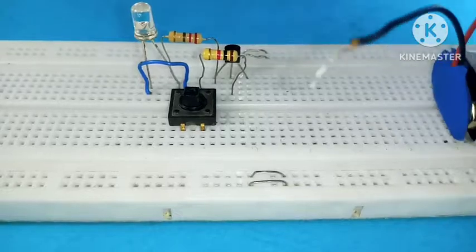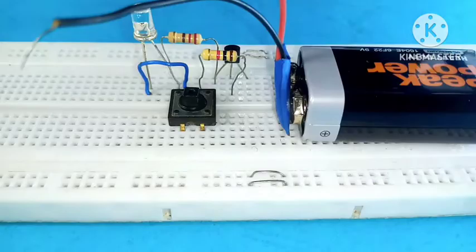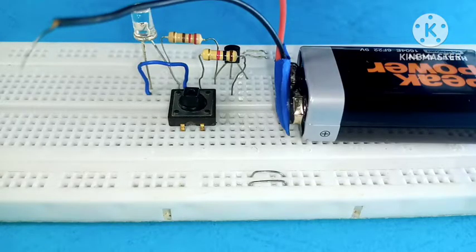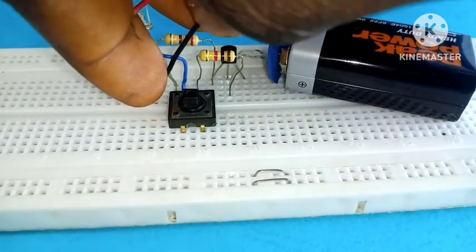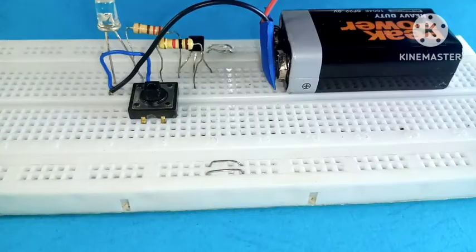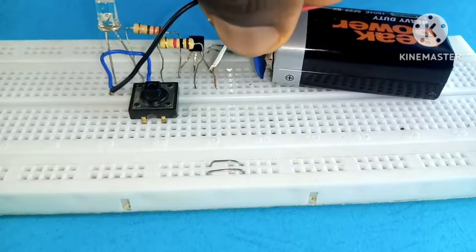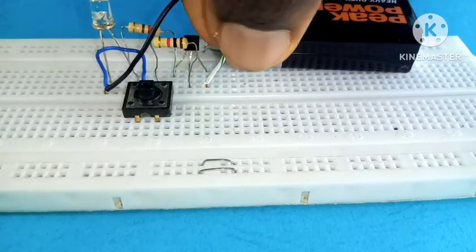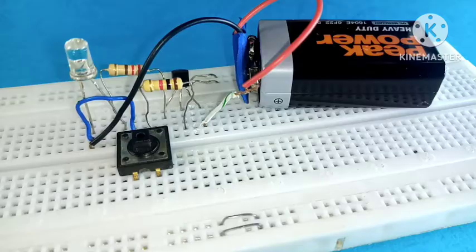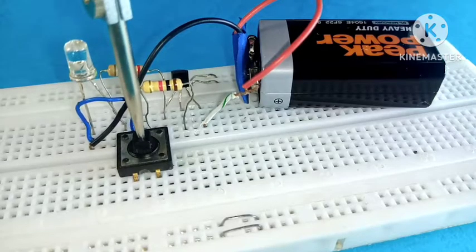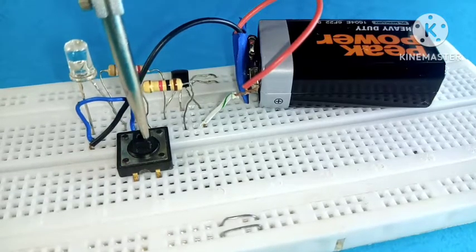Now watch, you will notice that the battery came from my right hand, but before in the NPN it came from my left hand side. So connect the negative polarity of the battery to the cathode of the LED, and the positive polarity of the battery to the emitter pin. Each time we send the base pin to ground by closing the switch, you notice our LED turns on.